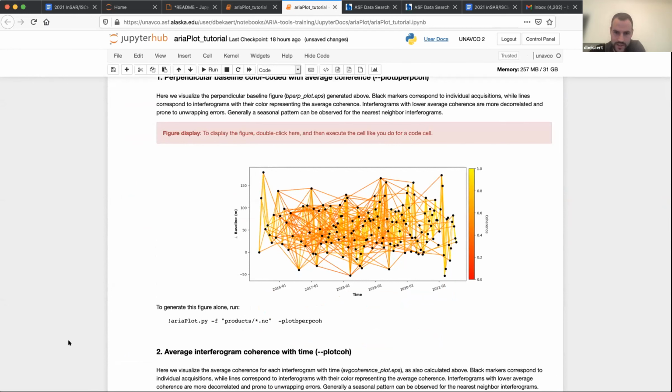And I was referring in the past to these more decorrelated interferograms, which are generally the annual interferograms. If you're making an annual interferogram from summer to summer, that might be good. If you make it from winter to winter and there's snow in winter, then generally that would not be good. If you do it from a monsoon season to a monsoon season, generally it would be decorrelated. But if you take a period which is good and coherent, and you go 1 year later, and that's again a coherent period, then that would also be a good interferogram.